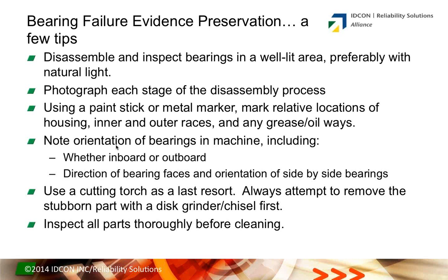Another thing that's important is, as I'm pulling the bearing out of the housing, I mark the location of any grease zerks, grease fittings, and mark the relative locations of the housing, how the inner ring and outer ring were located in the housing. That's essential to understanding the wear tracks and everything in the bearing, and it's something that's very rarely done. It can be as simple as a mechanic putting a dot on a race as they disassemble the machine, and it can tell you huge amounts of information as to why the bearing failed.